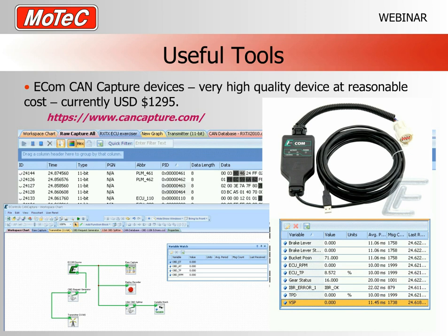Now these screens just below, they're not in terribly good detail, but what you can see here is a picture of the device itself, which just plugs into the USB port, and then it comes out to a CAN adapter of various types. We normally rewire these with a different type of plug. We just put DTM plugs on them. So this just installs on a normal laptop. It only logs CAN data while it's connected to the laptop. But in fact, we use little $300 netbooks for this sort of thing, and you can even run them in boats or in jet skis without any problems.